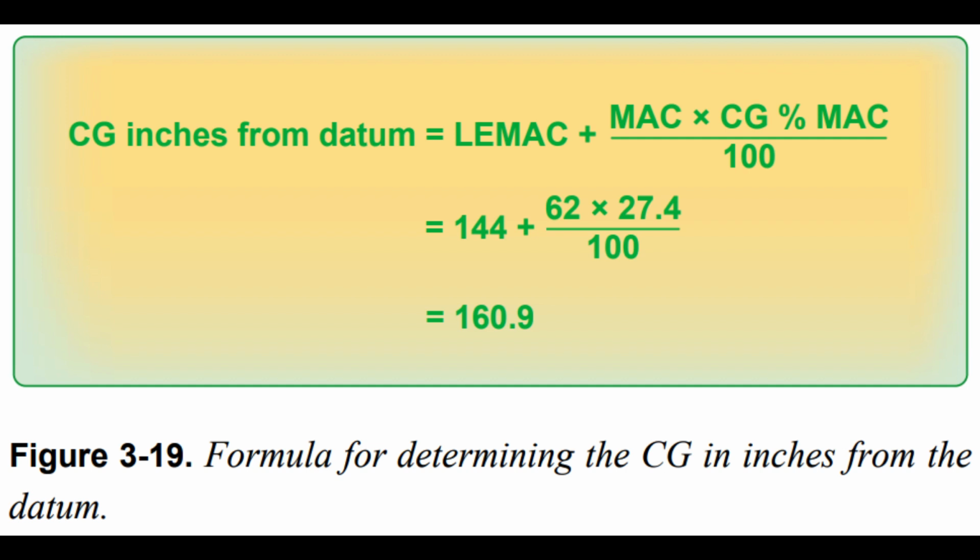It is important for longitudinal stability that the CG be located ahead of the center of lift of a wing. Since the center of lift is expressed as percent MAC, the location of the CG is expressed in the same terms. End of page 3-9. End of chapter 3.